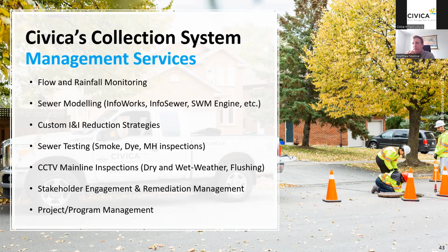There's quite a few that I've seen where they put rain gauges kind of close to the edge of the roof, and there's a lot of wind shear that comes up off the side of the buildings, and it actually kind of blows the rainfall up and away from rain gauges. So if you do put them on roofs, do not put them close to the edge at all. That's one recommendation.